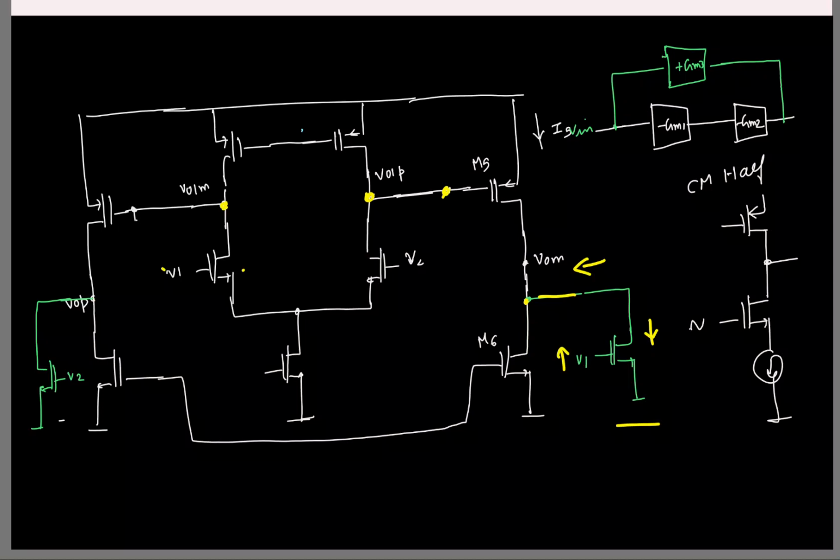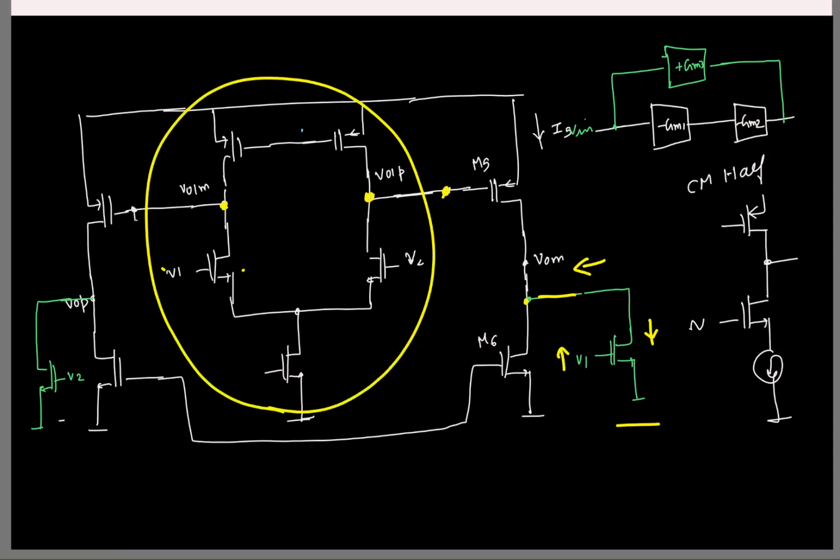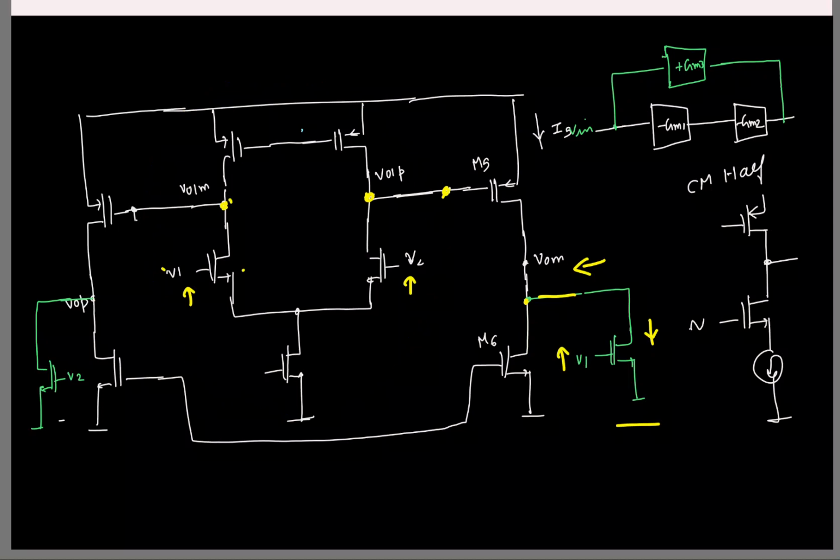Another one stage OTA. Yeah, what do you mean another one stage OTA? Okay, or to start with, see, in this stage, looks like even if I change the inputs here, the outputs don't change, right? What was making the outputs not to change? This guy was fixing the current in the transistors to some constant value. I mean, if you think about it, this is what is giving common mode rejection here.